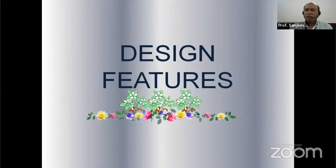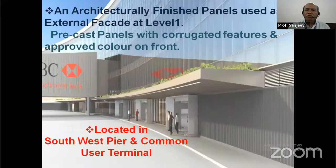So next comes the design feature. The design feature for the precast wall panel was an architecturally finished panels used as external facade at level 1. So level 1 where the people are standing in the photograph. That is the place where precast wall panel has been constructed in the vertical corrugated form. Precast wall panels with corrugated features and approved color on the front, located in Southwest Pier and common user terminal.